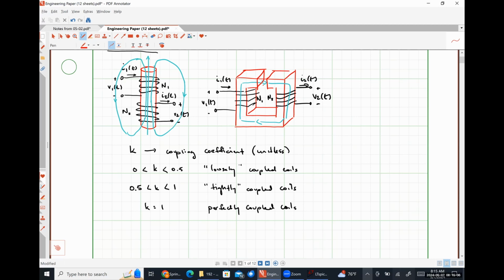It takes you applying a current in the opposite direction, and depending on the type of material and a couple of other things, maybe a significant amount of current in order to fully demagnetize the material. So permanent magnets are actually made with electromagnets. It's just their material properties that allow them to hold on to magnetization even after the current is taken away.